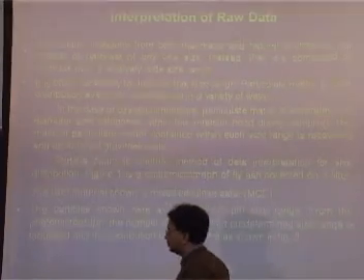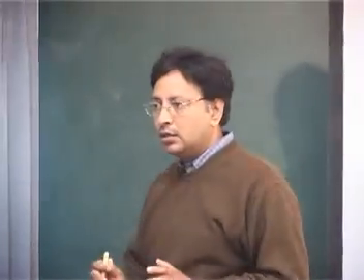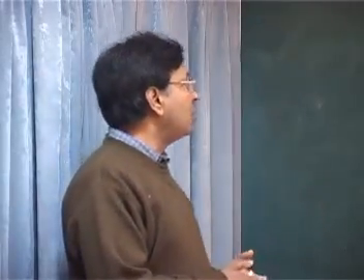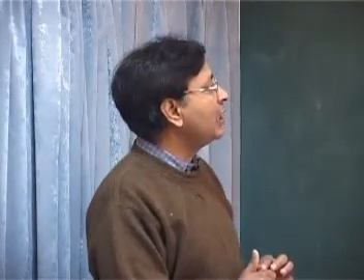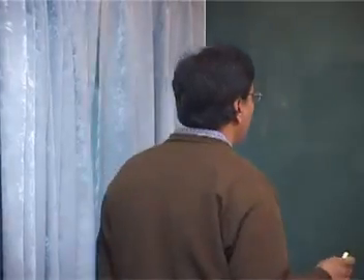See, when it comes to the matter of interest, either when you are controlling the particulate matter, or you are trying to see what the particulate matters in the atmosphere are, size is very, very important, especially from the health point of view, and also for the way you have to design a system. You want to design a system for the particle size you want to remove. So the system which segregates the particle size uses the advantage of something called a cascade impactor. It is based on inertia.